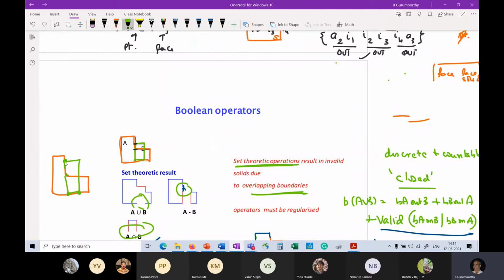So here, while you are right that this point on the boundary of B lies on the boundary of A, the dimensionality of the point is 0, whereas the set I'm classifying is actually the boundary of A, which is edges, of dimensionality 1. Therefore, these will not be used in the result at all. They will not be taken up as a result of the set membership classification. Okay, and so we don't have to worry about this. Okay, sir. Thank you, sir. You know, because of the second condition.